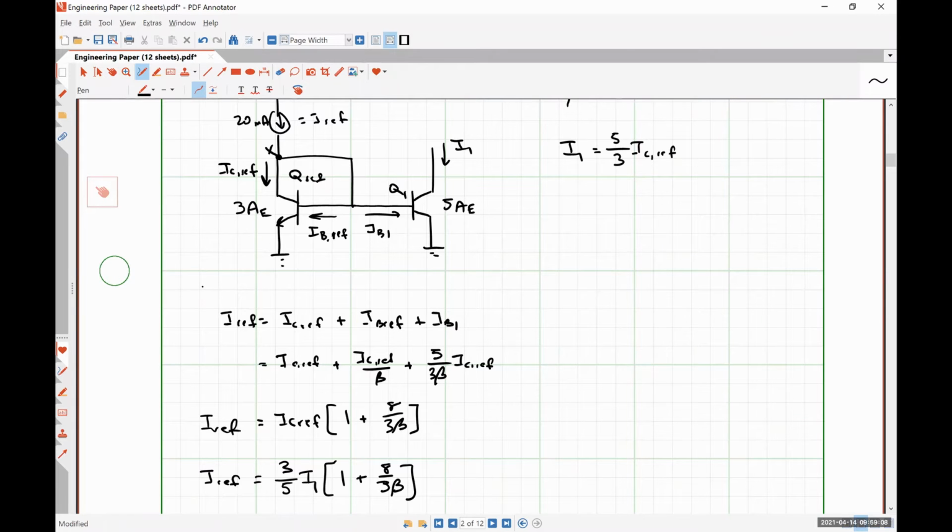If you have a finite tail impedance, as we proved in class on Monday, and either a transistor mismatch or a resistor mismatch, you will see that a change in common mode signal level causes a change in the differential mode output. That conversion gain is simply the ratio of how much change in output differential signal we see due to a change in input common mode signal.